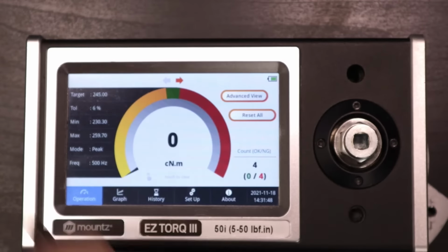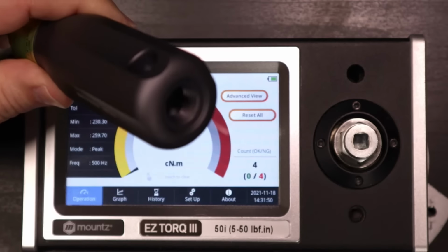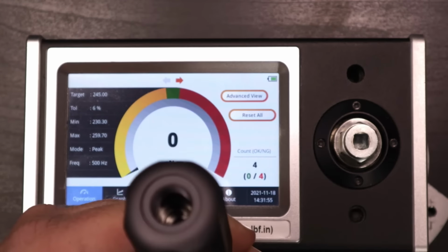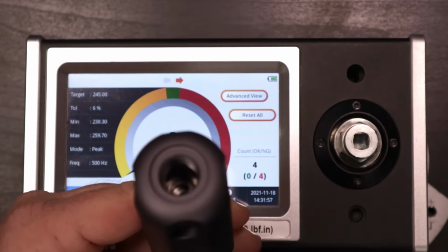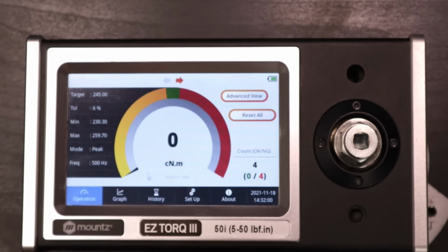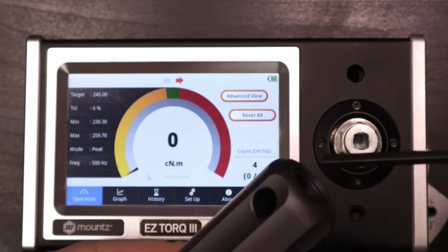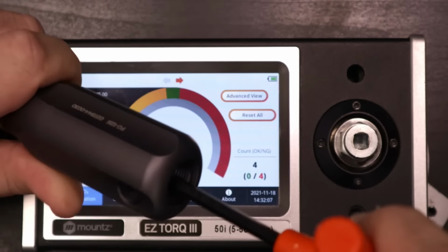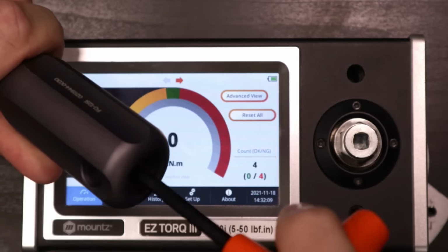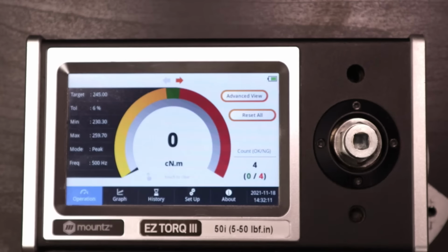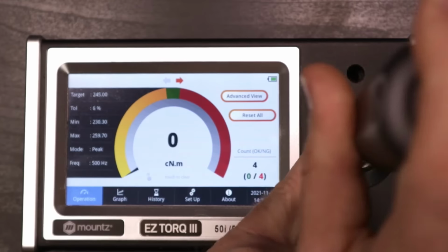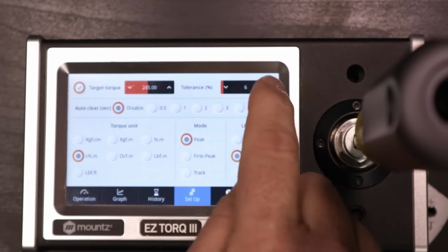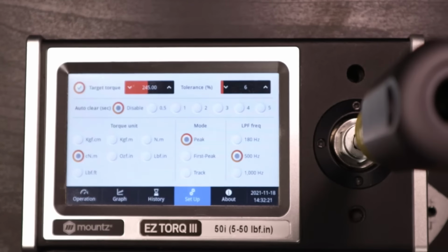We have an end cap that goes on the back of the tool here. Down below, there is a torque mechanism down here that we would loosen the locking mechanism. And then we can come into the back of the tool with the adjustment key and go ahead and turn it clockwise. That's going to go ahead and increase our torque value. And let's go ahead and change our value on the analyzer.